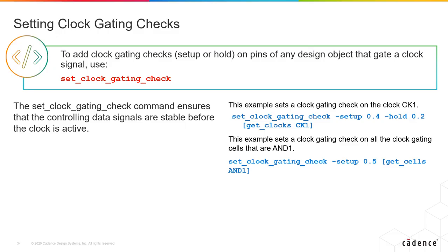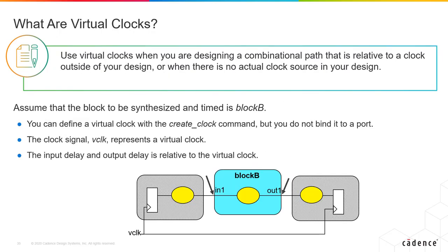So if you want to model the real nature of a clock, you need to add the transition times and ensure that these clock gating checks apply to the ideal clock. The clock gating checks are built in with some values in the libraries themselves, and make sure that these checks are performed on the falling edge. So you might not need to set any additional values, calling the clock object, and the clock object will indirectly call the related ports.